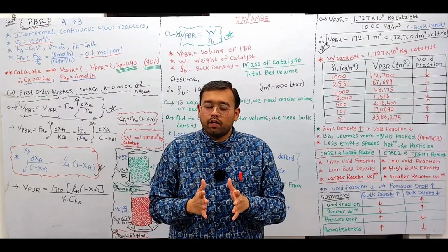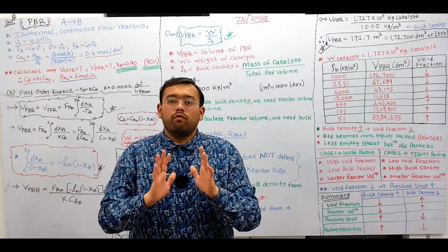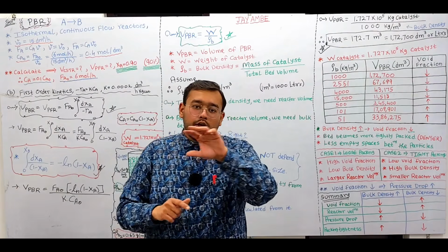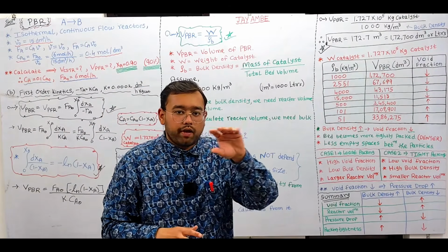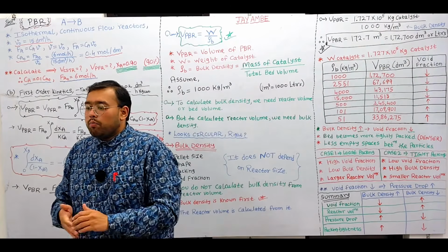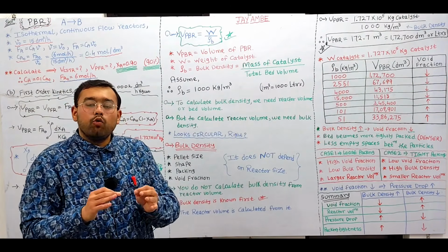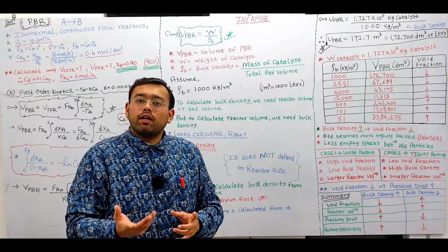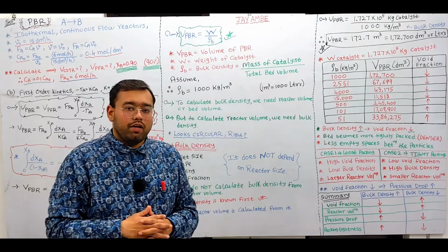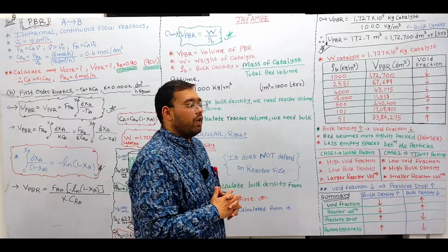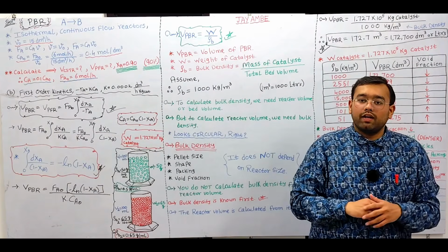In the case of the plug flow reactor, the entire hollow space of the tubular reactor is completely vacant, completely empty, and the fluid passes through the tubular space and the reaction takes place. But in the case of the Packed Bed Reactor, the hollow space of the tubular reactor is completely filled with packing materials, such as solid catalyst. Due to those reasons, the Packed Bed Reactor differs from the plug flow reactor. I hope up to here you have understood. But both the reactors are tubular reactors.